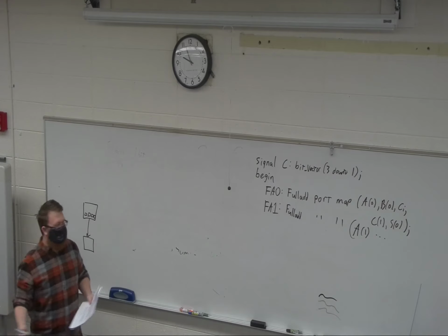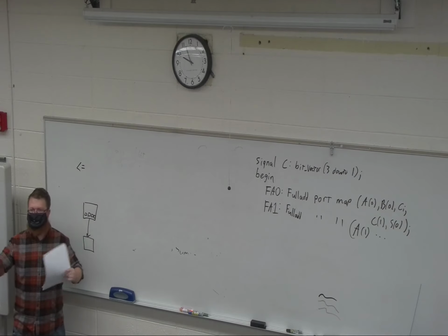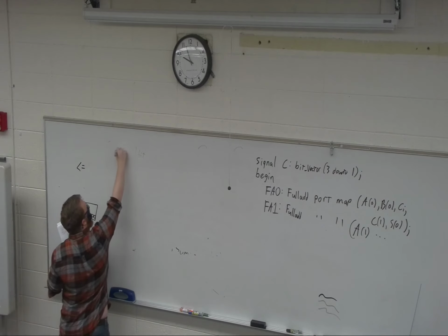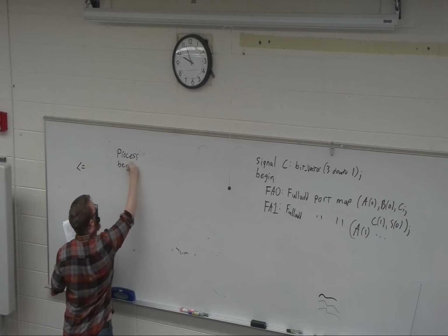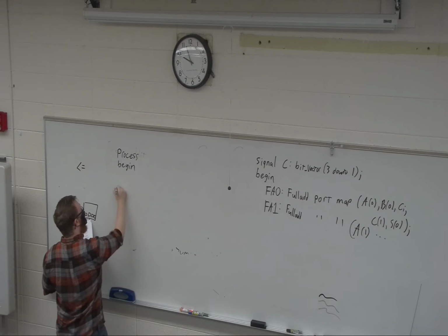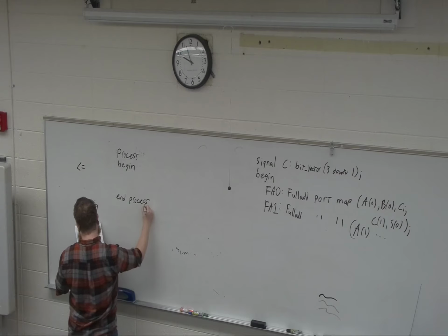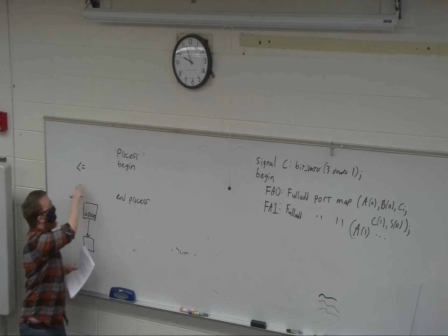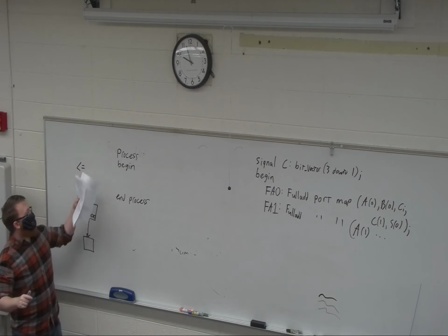You recall how I said, if you write this symbol and you have a bunch of statements, they all act at the same time. Well, here's the exception to that rule: if you call something a process. And you would put sequential statements in here. So you write them the same, but they are going to go one, then the next, then the next, then the next. They're not going to all react at the same time if it's in a process.